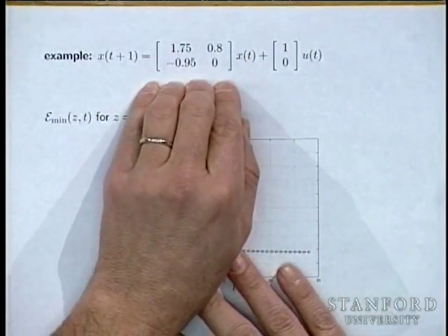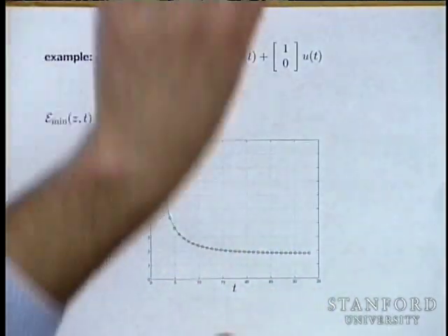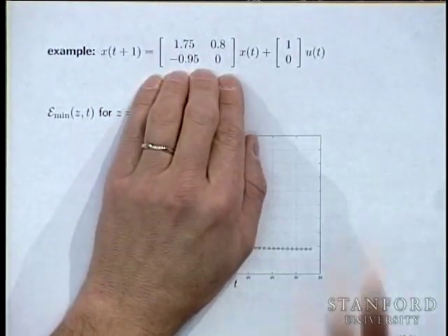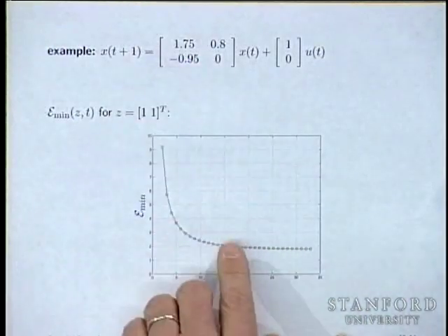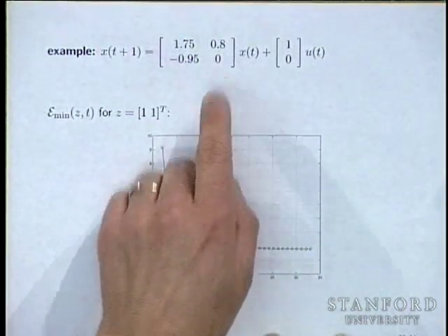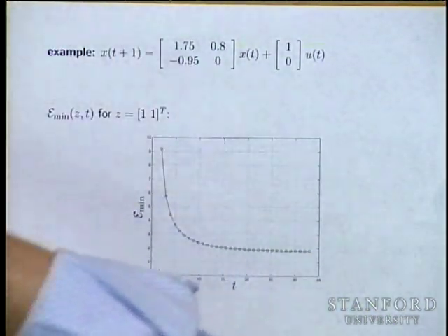Anyway, so the conjecture is that this is actually, well, I'm not sure about the eigenvalue thing. We'll see. What I was going to say is this: if a system is stable and you have to get somewhere, you actually have to fight the dynamics to take it out to some place. Because if you take your hands off the controls, if you do nothing, the state will just decay back to 0. So you're swimming upstream when you're doing reachability for a system that is stable. Okay?